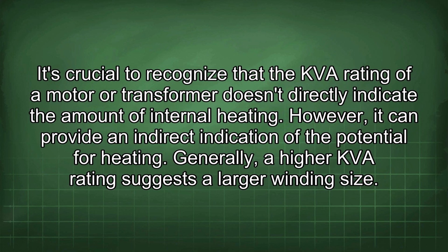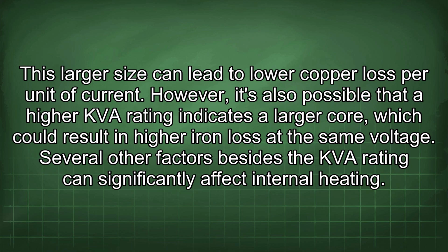It's crucial to recognize that the kVA rating of a motor or transformer doesn't directly indicate the amount of internal heating. However, it can provide an indirect indication of the potential for heating. Generally, a higher kVA rating suggests a larger winding size. This larger size can lead to lower copper loss per unit of current. However, it's also possible that a higher kVA rating indicates a larger core, which could result in higher iron loss at the same voltage. Several other factors besides the kVA rating can significantly affect internal heating.